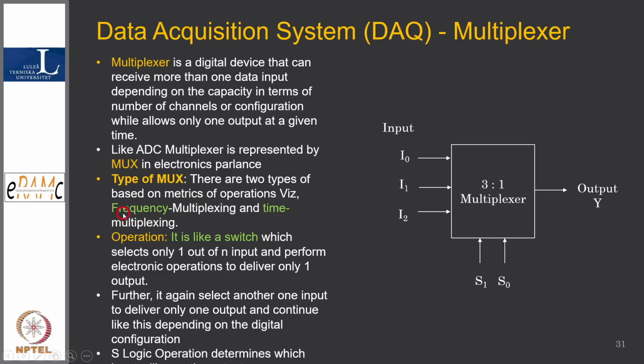Why? Because I want to understand the predominant frequency for failure. An experienced vibration specialist might say these two peaks are high, and that it is an inner race failure for the bearing.